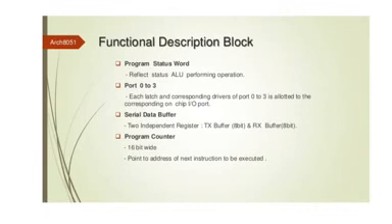So here you generally have 4 flags. For math operations you have 4 conditional flags: carry flag, parity flag, overflow flag and auxiliary carry flag. Coming from the lowest order, first you have the parity flag at the D0 bit.